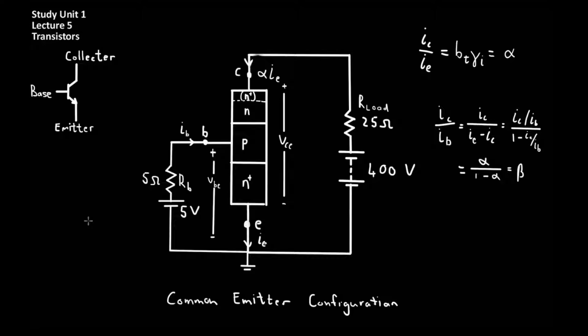The bipolar transistor, or BJT, consists of a set of PN junctions in either an NPN format or a PNP format. The reason a bipolar transistor is called a bipolar transistor is because it works by injecting both minority and majority carriers into the silicon. Essentially, both transistor types are used as switches or as gain elements and work by controlling current.